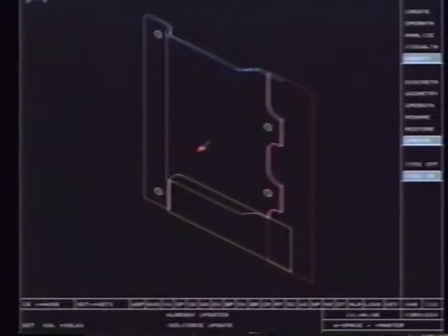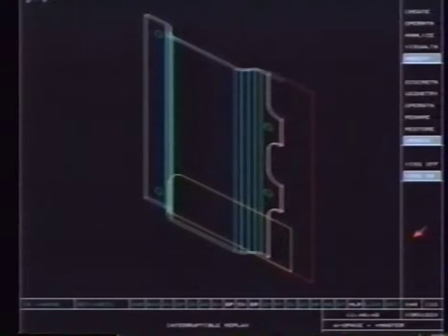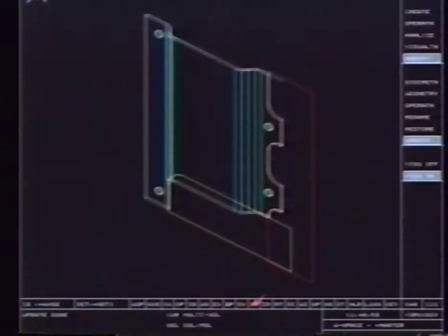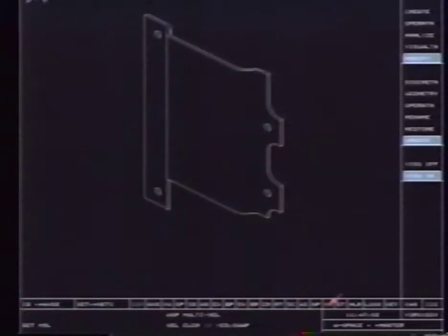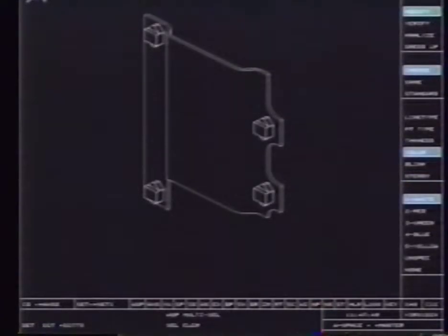In most cases, solids representing the parts are created by projecting a closed curve a specific distance and then subtracting other solids from it to create the desired shape. This type of operation is similar in nature to the machining process which makes actual parts. Once the basic design is constructed, standard parts obtained from a library are added to make the design complete.